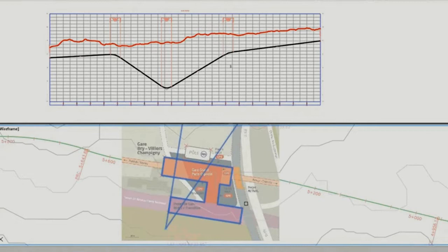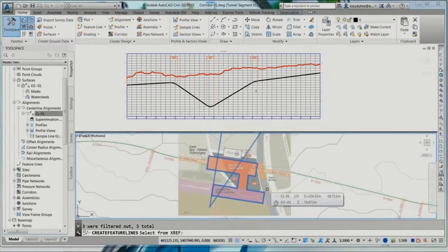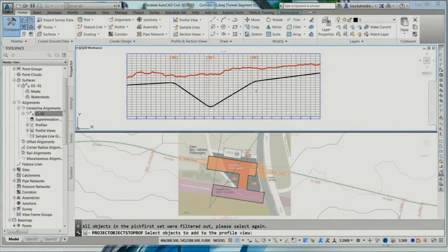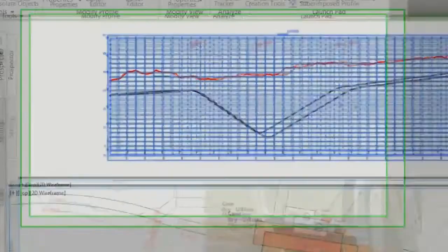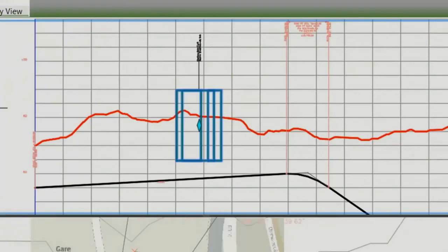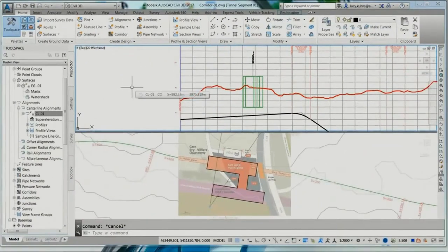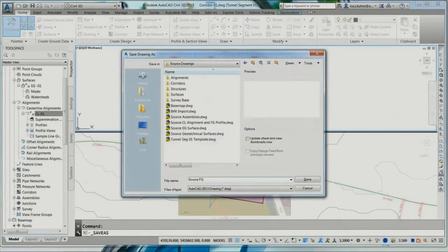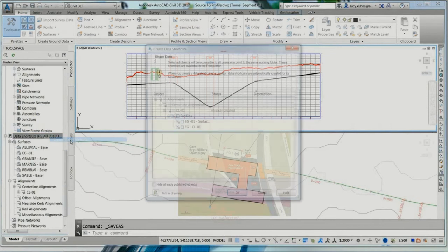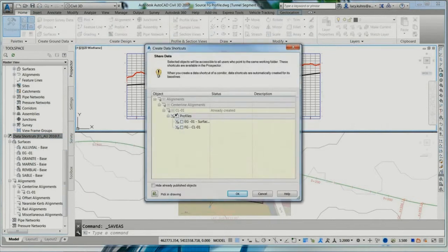First we put in an XREF, and I'm going to put in an XREF just so we can see what's going on behind the scenes, and that's the little house. Now what I'm doing is from that XREF, I'm actually putting, not a house, it's the station, and I've pulled out of that XREF, I pulled the 3D model out of the XREF. Did you know you could do that? That you could pull CAD right out of an XREF. And then I put it in the profile view because it's a 3D model.